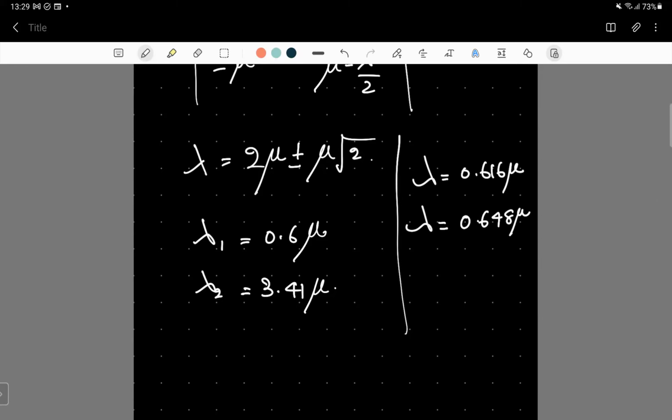So it is clear that for bar elements, sometimes specifically for bar elements, the lump mass approach can provide results as good as the consistent mass matrix approach. Sometimes even better. Right. Now, having said that, we are mainly interested in calculating the first and the second natural frequencies.